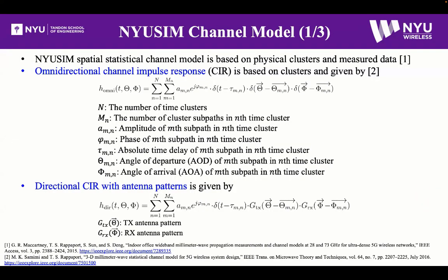Now, in order to understand how the sub-terahertz band behaves, it is important that we create models to understand the propagation of radio waves in these bands. This slide, without going into details, just captures a high-level mathematical overview of how you can represent a channel impulse response, which is basically how your multipaths in the environment can be captured in a mathematical form for omnidirectional and directional antenna patterns.